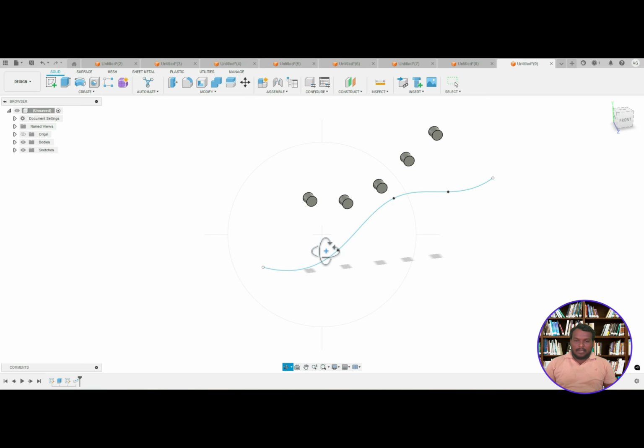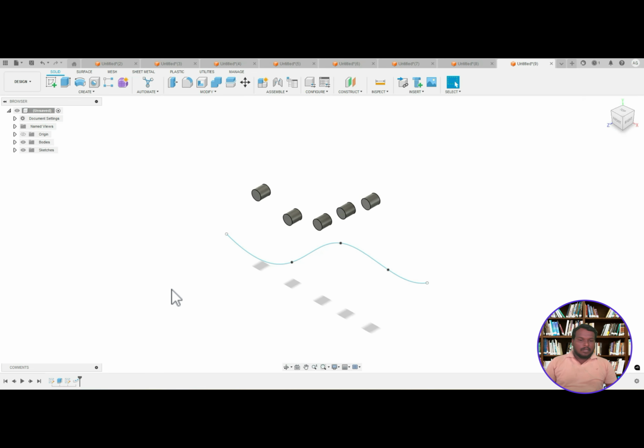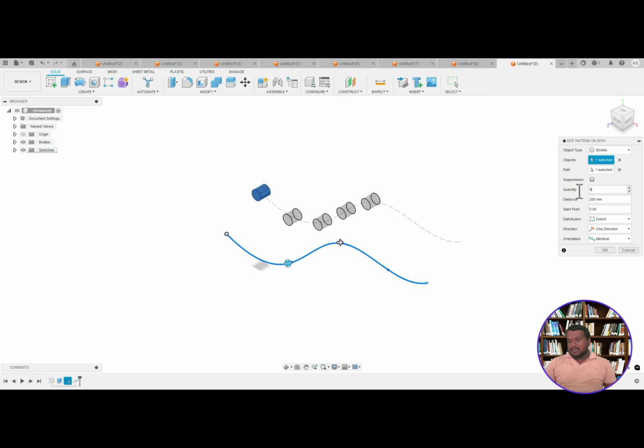See that? This is one point like that, coming and going, from here coming like that and going. And we'll add some quantities. Click on home position, we'll come to home position. Click on circular path, edit pattern. We'll give 10. So distance between spacing. One direction means not symmetric, one direction spacing. This is 20 mm.